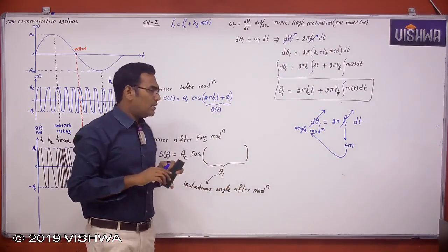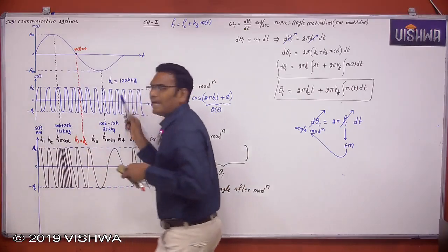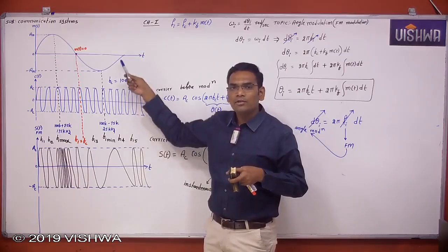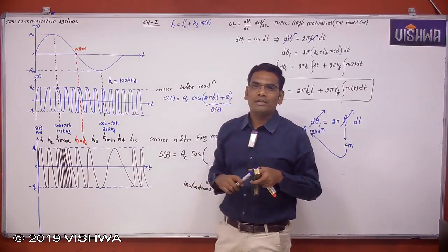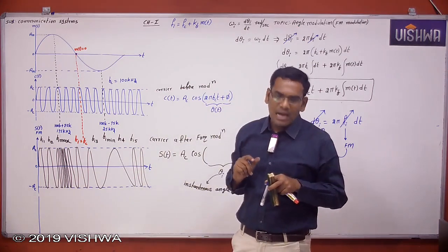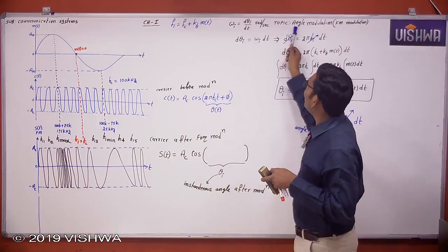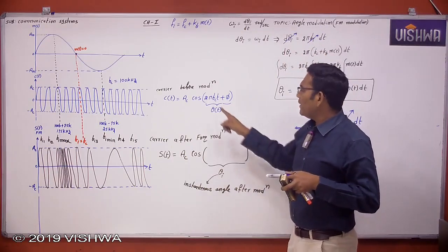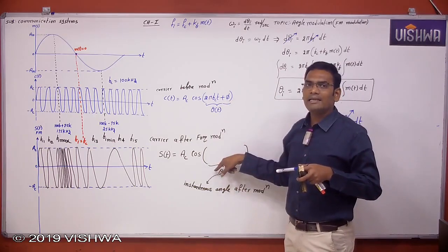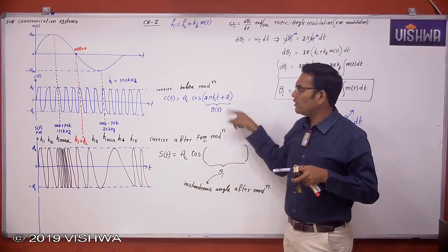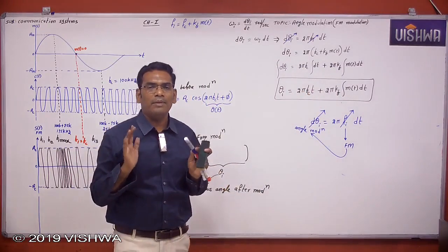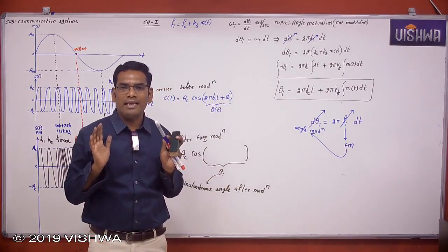Of course, the message is analog, the carrier is analog, the modulated signal is analog, continuous wave modulation, analog modulation. In that, AM, FM, PM, these two, FM and PM, are classified separately as angle modulation, because when frequency changes, angle changes, and when phase changes, angle changes. Now it is clear or not? Previously you had some doubt why it is called angle modulation.